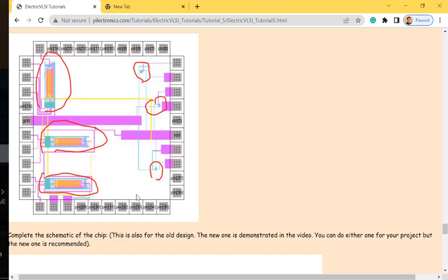And the most advanced technology available right now from TSMC, a couple years ago, was 7 nanometer technology, in which every single transistor can be fabricated with like a 7 nanometer channel size. And most recently, I think the 5 nanometer technology is gaining some momentum. It's available commercially, probably from last year. And 2 and 3 are still being developed. I don't know when they will be available, but it's reaching the limit right now.